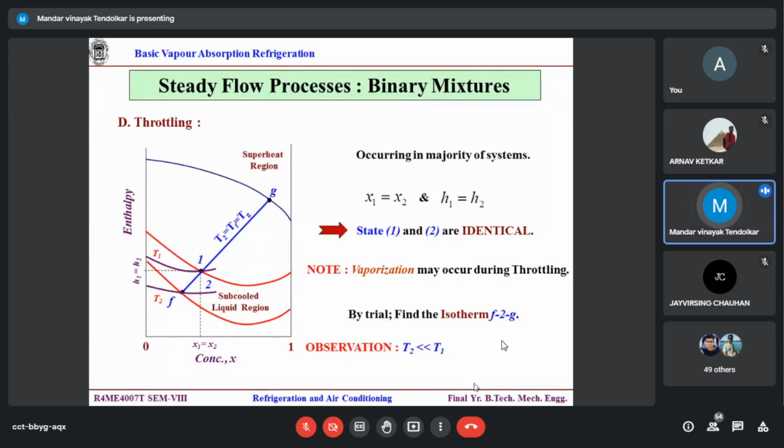If I ask the question for the air refrigeration, you can write down T1 equal to T2. But in air refrigeration, we go for the isentropic expansion, not the isenthalpic one. We use the turbines. Correct? Any doubt, online people? No, sir.